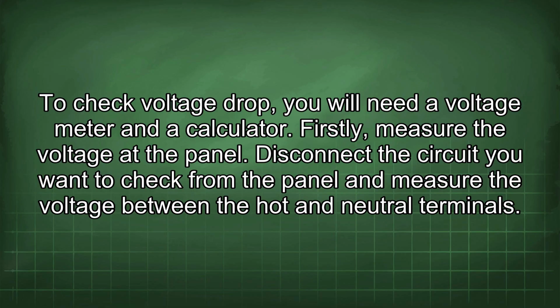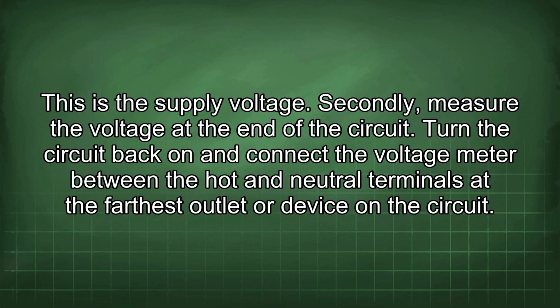To check voltage drop, you will need a voltage meter and a calculator. Firstly, measure the voltage at the panel. Disconnect the circuit you want to check from the panel and measure the voltage between the hot and neutral terminals. This is the supply voltage.